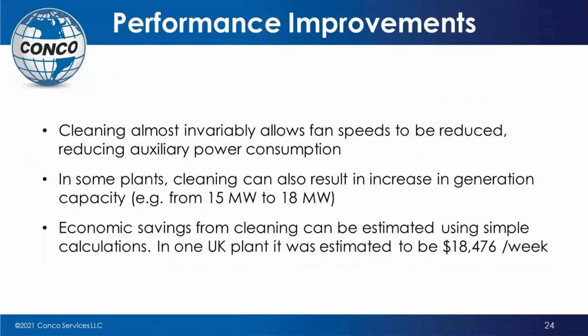It allows the fan speeds to be reduced because they're not running into a higher pressure. The air itself is able to go up and move freely through those fins. Because you're utilizing all the space and all the fin capacity, you're able to get a much more efficient and effective condensing using this particular type of application. And in some instances, you can see an increased generation capacity as a result of the cleaning itself.